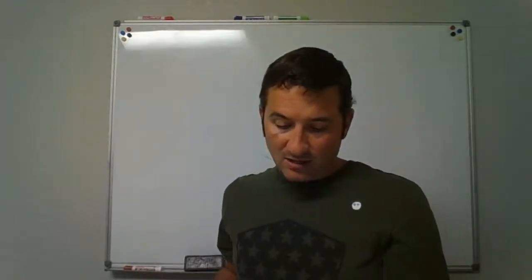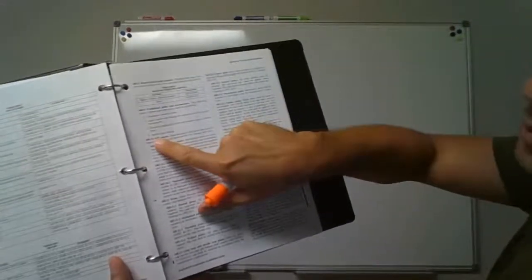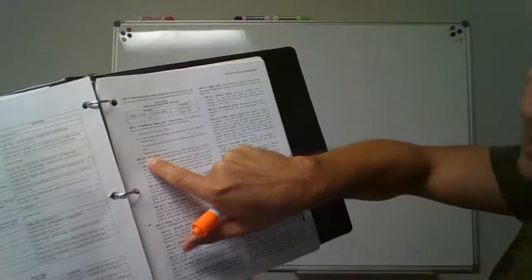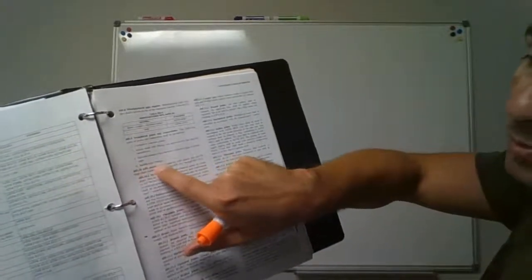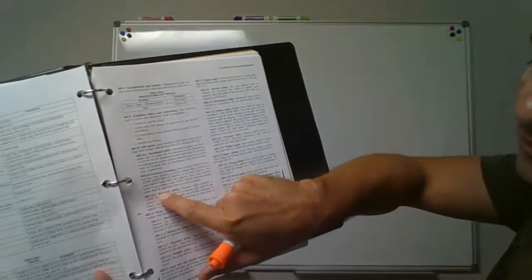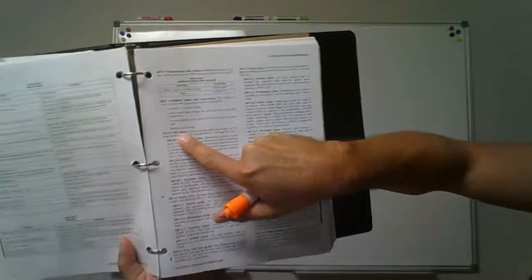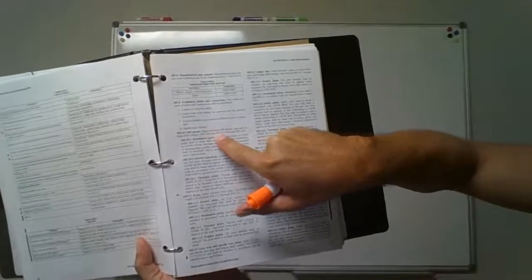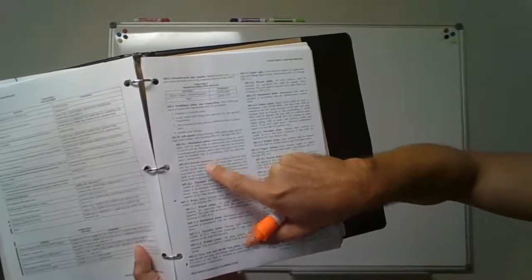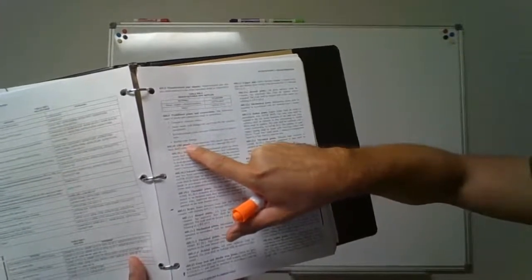Let's see. And then how you're going to read the rest of this? 605.10. Okay. It's got the .10. Now, underneath .10 is going to be .10.1, .10.2, .10.3. These are all breakdowns underneath for ABS plastic pipe. So for ABS plastic pipe, how can you do joints between those? Well, you can do mechanical joints, you can do solvent cement joints, and you can do threaded joints. All of these are approved for ABS plastic.